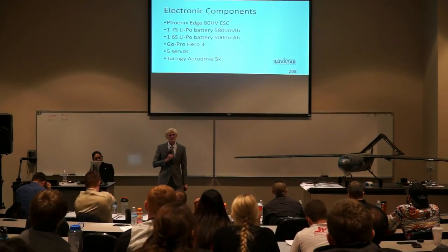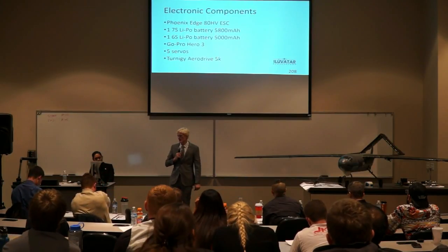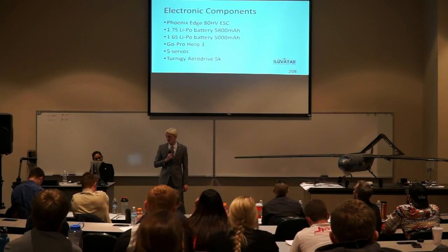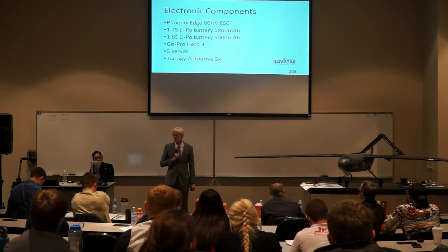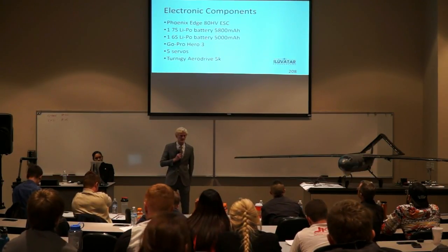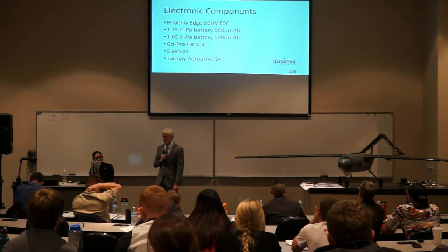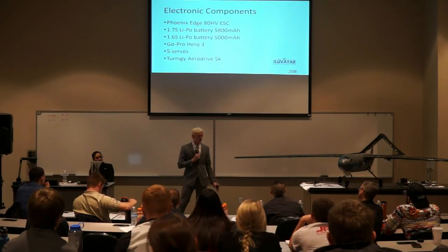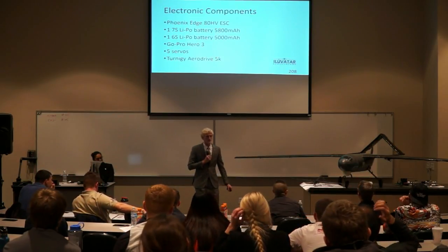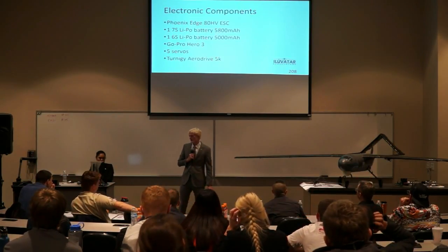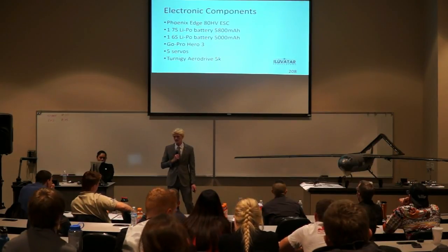The electronic components that we used were a Phoenix Edge 80 HV ESC, as well as 2 LiPo batteries, one 7-cell and one 6-cell, totaling about 13 cells of LiPo batteries. And we also had a GoPro camera that we put on the front so that we could record our flight, 5 servos, and an Eternity AeroDrive 5K motor.